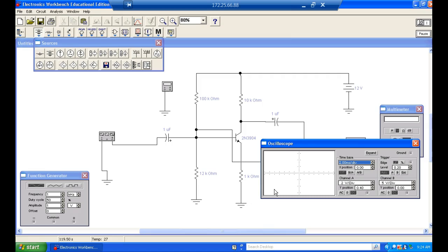Why? Oh, we got 12 to work with. That's exactly right. So that means we need to lower this input voltage a lot. So 10 millivolts, I got a gain of 10, that would be 40 millivolts out. So we could probably put 50 millivolts.